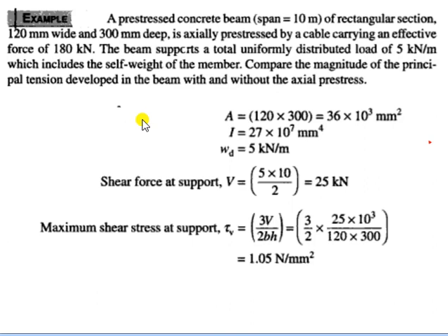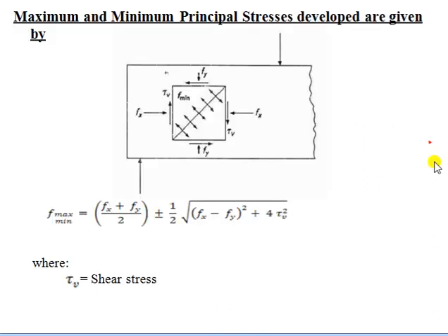So you remember the equation. This is the formula we need to use. So here I told you this is prestress in horizontal direction, prestress in vertical direction. In the question they have not given anything about vertical or transverse prestress. Therefore this term is 0. f of y will be eliminated because they have not given anything about vertical prestress. They have given the value of f of x.